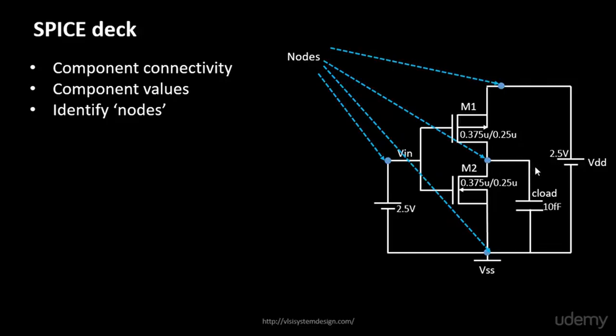Okay, so there is nothing other that is coming in. Had there been a resistor over here, then there would have been this node and there would be another node which is present over here. Since there is nothing present between this point and this point, this can be considered as a potential node. So these nodes are basically required to define your SPICE netlist, and I'll show you in some time from now how basically these nodes are important. Similarly, if you look into this, VDD can be very well defined between this node and this node.